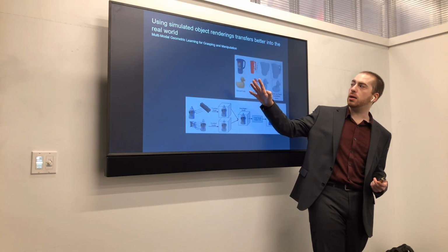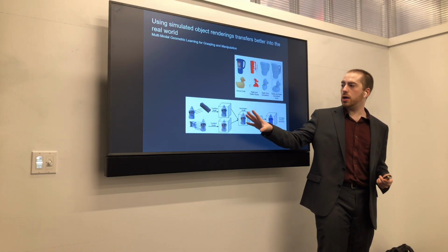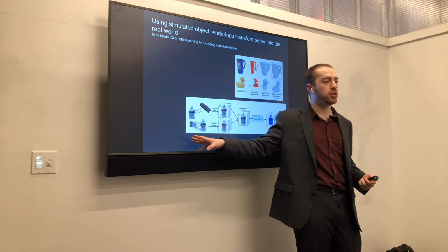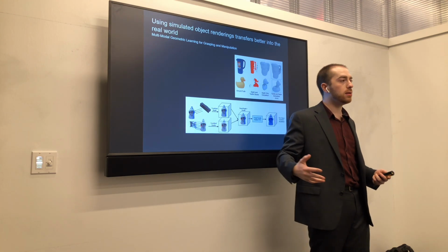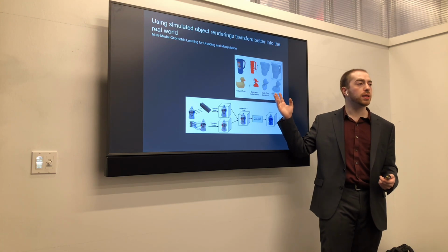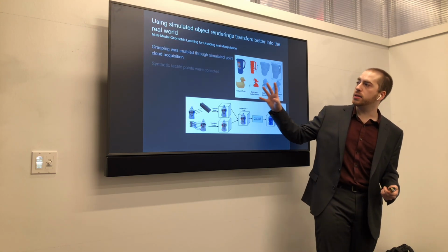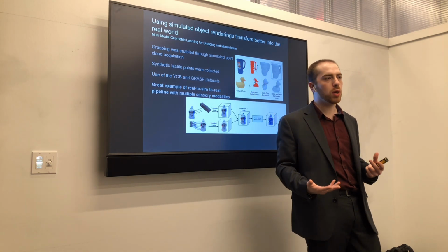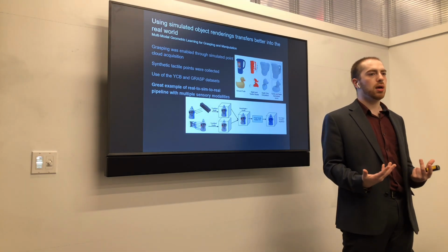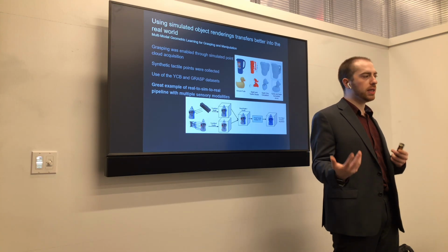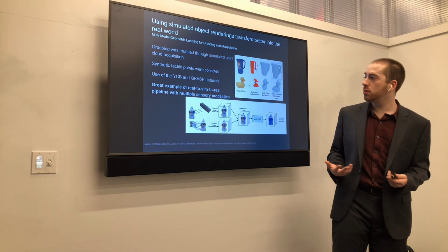A paper that I wrote recently took two modalities of input, both RGB and RGBD, and then also tactile data collected from the occluded side of the object, and was able to predict geometry of those input point clouds. And so what I'm highlighting here is we don't need just real to sim to real using just one sensory modality. We can take multiple to solve these problems and approximate geometry better and more accurately for the physics simulation to perform better.